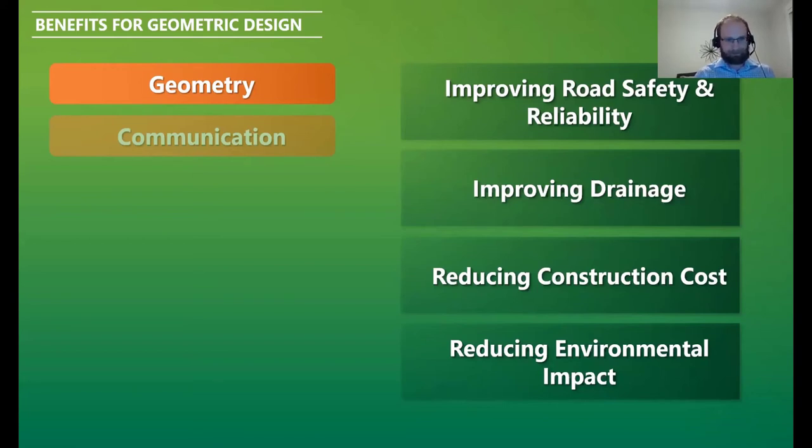pipes, if you're putting your culvert in a large fill on a heavy skew, you want to make sure you have the right length of pipe when you go to build that crossing. So you've got the geometry there, you can skew it, you can adjust your grade, you can look at the 3D view and place it exactly the way you want and know that that's an appropriate length for the crossing.